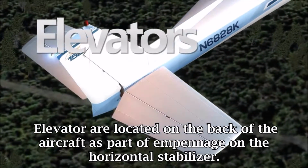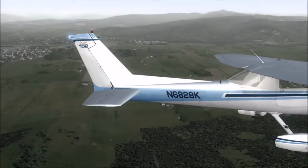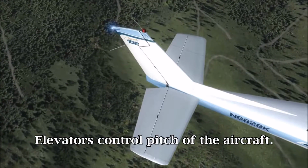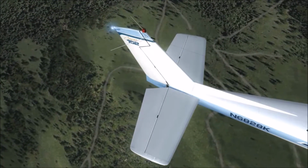Elevators are located on the back of the aircraft as part of the empennage on the horizontal stabilizer. The empennage is basically from right behind the wings and the remainder of the back of the aircraft. Elevators control pitch of the aircraft. In other words, you can change your angle of attack with these controls as you learned before.